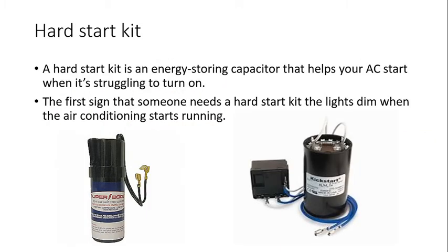Hard start kit. These are called by different names. They're called a hard start booster, a kickstart. They call them a lot of different names. And what it is, is just another capacitor that stores power in its body. So when a system comes on, it will help the compressor move. If this was a 3-phase system, you wouldn't need it, but in single-phase systems, you need them.